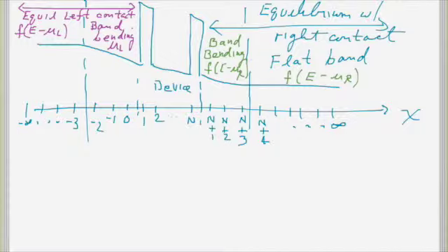And the device is our non-equilibrium region. In the device region, the filling is not an equilibrium distribution. It's not determined by an equilibrium Fermi factor. To get the charge density, we have to calculate G sub n in the same way we talked about in chapter 1. So that's the setup.